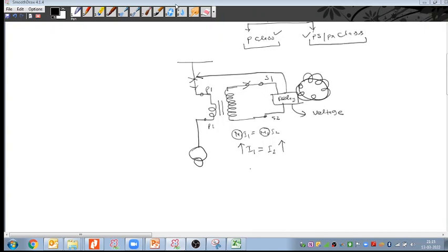So the fault current is going to go through the secondary of the transformer, and you have a burden or a resistor inside the relay, which is going to cause a voltage drop. Is that the voltage you are talking about for the CT saturation? Basically, what happens is, if we go to the relay catalog, the relay requires some voltage.